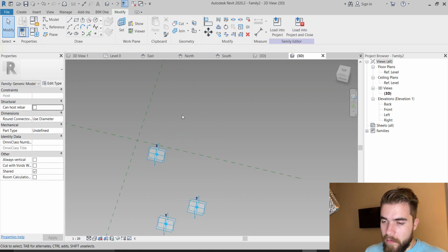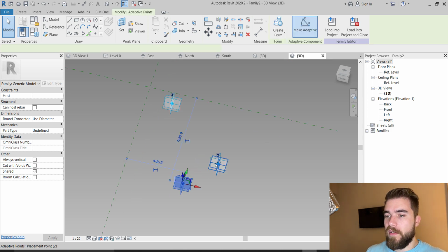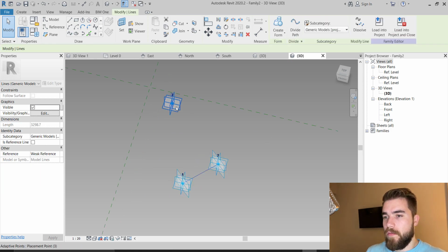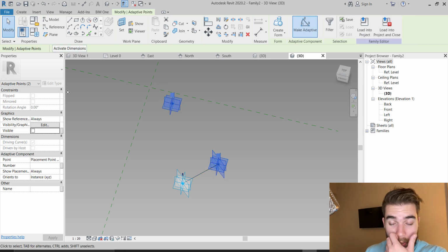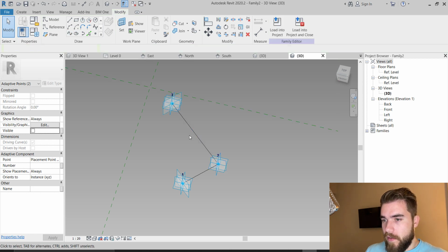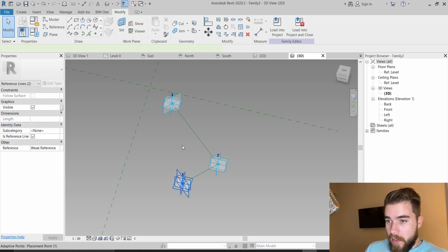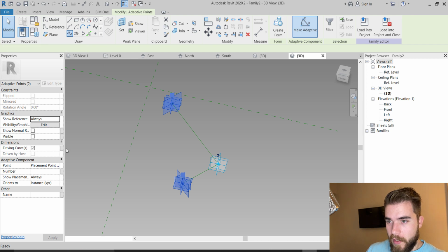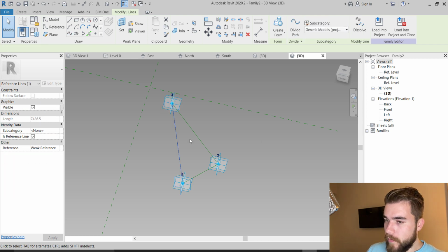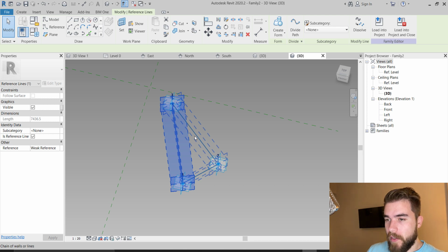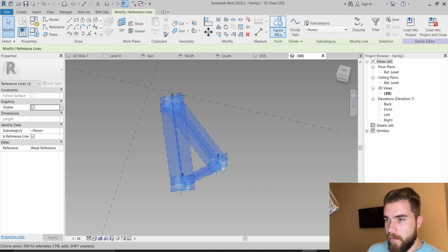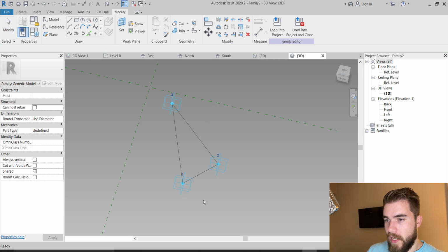And I'm going to do pretty much the same exercise here, creating those splines through points. A spline through 2 points is basically a line. I need to make sure it always goes through the points. That's why I'm using a spline, not because I need it to be curved. And I'm going to connect those two and create another reference line. And as you know from geometry, 3 lines create a plane. And I need that plane.